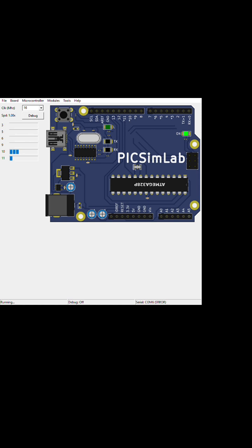Here we used LM35, which is a temperature sensor, and humidity sensors, and for controlling the machine we have used a push button switch, and this W5500 is used for the Ethernet for the whole embedded system, and this potentiometer is used as a vibration sensor, and this is used to connect to the ThingsBoard cloud where we virtually see the data, and these three LEDs indicate red, yellow, green. Green indicates that everything is perfect, yellow shows when there are any warnings, and red indicates whether there is any fault in our whole system.